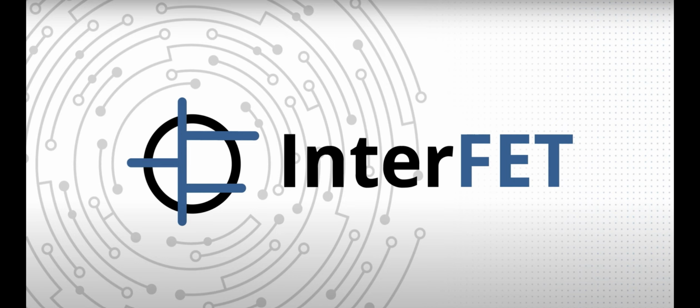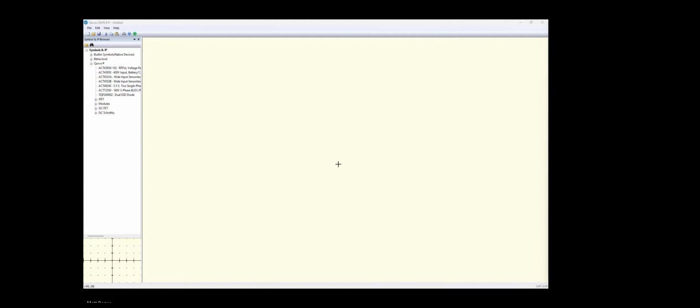In this video, we will simulate a JFET amplifier with QSpice. This is how the QSpice program looks when first launched after you dismiss the quick tip screen. We will build and simulate a JFET common source amplifier. To do so, we'll need a JFET. Luckily, QSpice has some built-in JFET symbols.